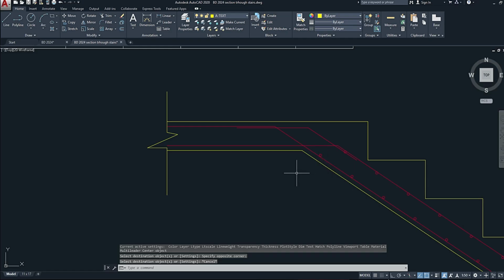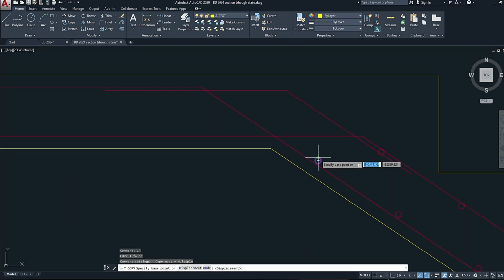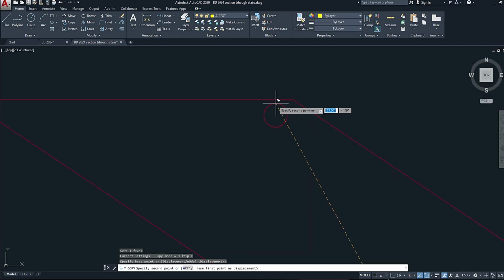All right. Now again, we have to add steels to this as well. So we are going to grab onto this one here, CP, enter, grab onto it, and then we'll place it again. One would be somewhere along here. Let me not snap to anything. And then now I can copy this steel from center to center. Let me turn on auto.